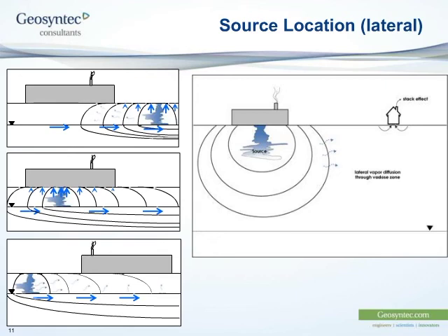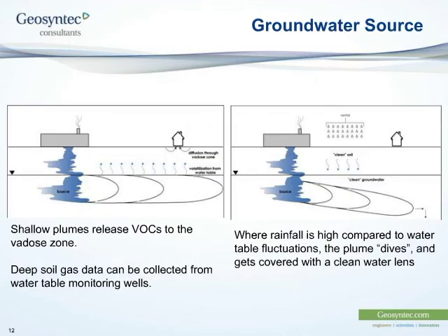If you have VOCs that have dissolved in groundwater and are migrating laterally, they can off-gas over some considerable distances. There are some sites where there have been vapor intrusion impacts up to 5 kilometers from the source area. If there's enough in the way of infiltrating rainwater that causes the groundwater plume to progressively get deeper and deeper and more removed from the water table, then there's less off-gassing to the vadose zone.